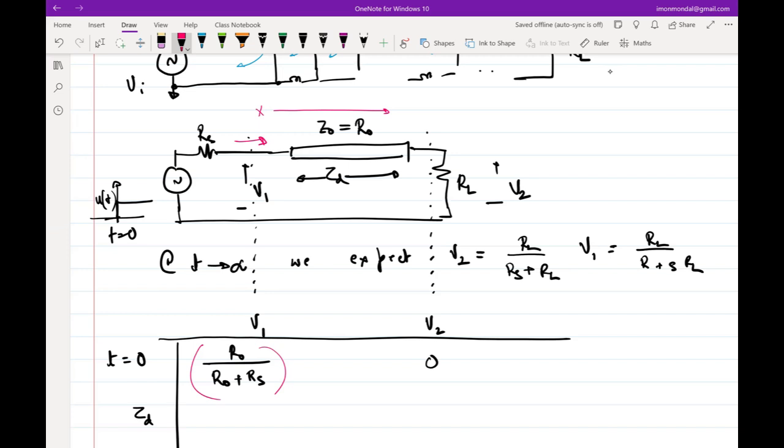Now it knows. Note that this type of argument is different from solving KVL, KCL the way we are used to. Because when we are solving KVL and KCL with lumped elements, we do not take into account what happens after the signal has propagated. We take the overall picture, assuming the circuit has settled. Here the circuit is still settling. So we can divide this treatment into what is happening after some time and what will happen after some time, and combine all the wavefronts and then figure out what the final settled value will be. It is similar to the way we talk about interference and diffraction in school. We say that a wave goes this side, another wave comes this side, and you can do the analysis for each of the waves separately and then sum them together, and you see your maxima somewhere, minima somewhere. Similar to that, you can think of these as wavefronts which are propagating along a line.